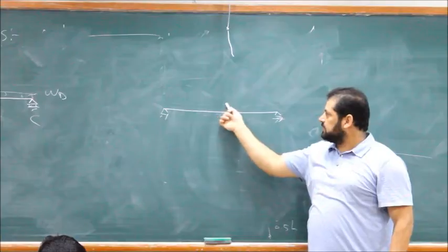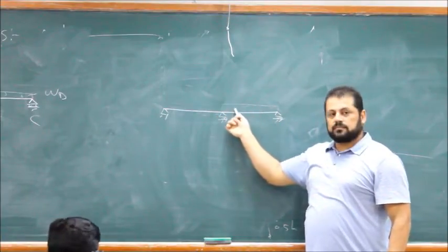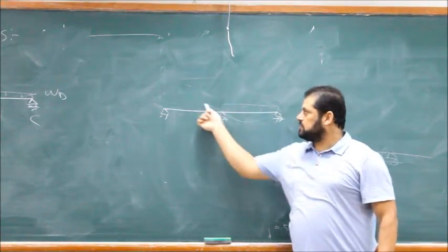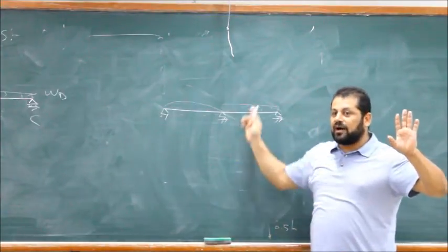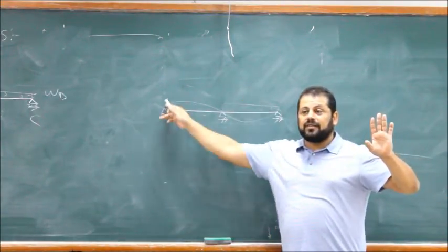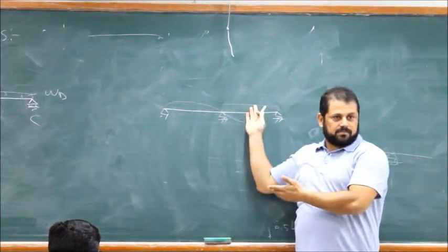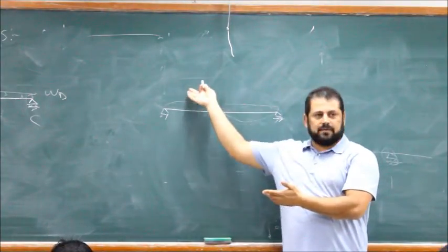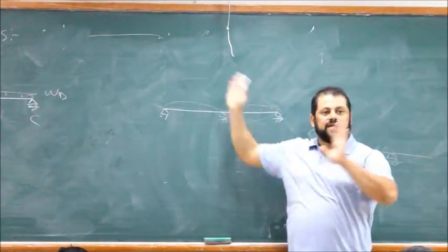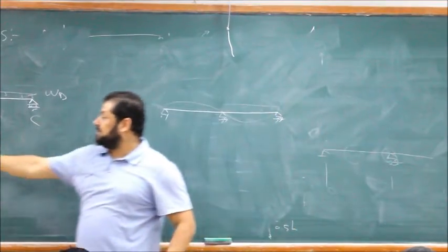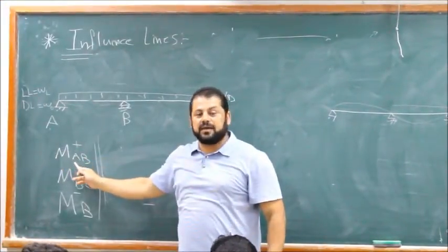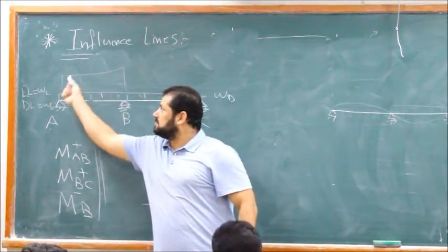Put live load here. This goes down, this goes up. It means if you have a live load here, the moment here will decrease. This will raise it up. It will relieve the positive moment. It means to maximize the live load in span MAB, we only load this.